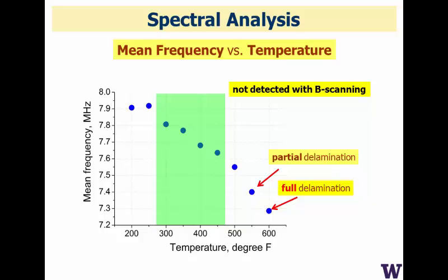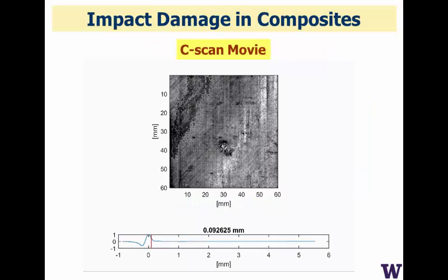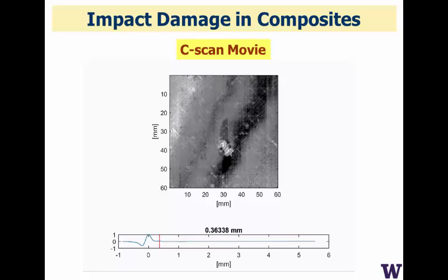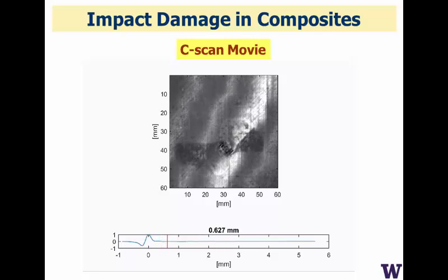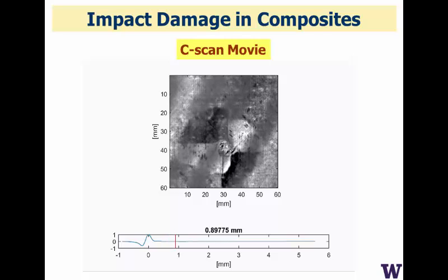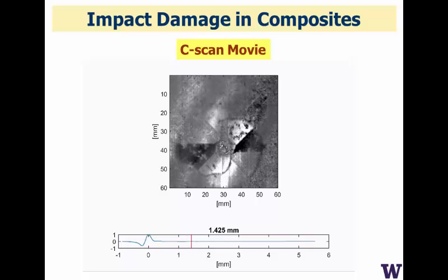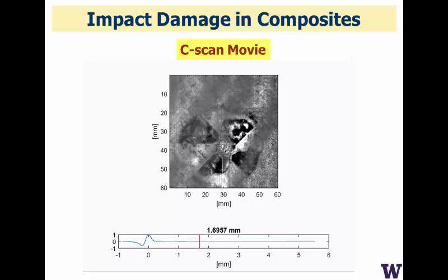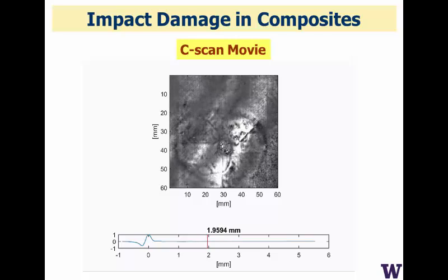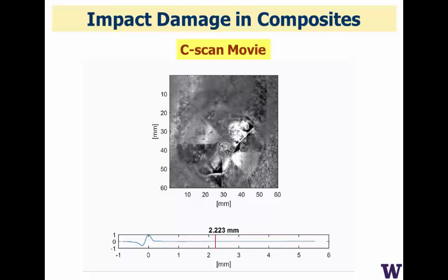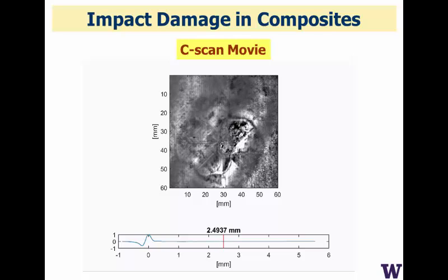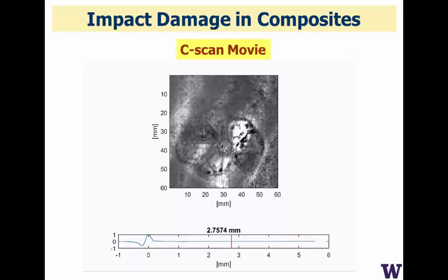And so this becomes, again, a high-speed, non-contact, in-the-field way to monitor heat damage on composites used in the aerospace industry. Okay, finally for composites, I'll show you the last example, which is looking for impact damage. So this is an alternate display method. Remember that we make B scans through the cross sections. However, because we rapidly scan, we can take that three-dimensional data set and rotate it and just display C scans going in through the depth of the composite. That's what we're doing here.